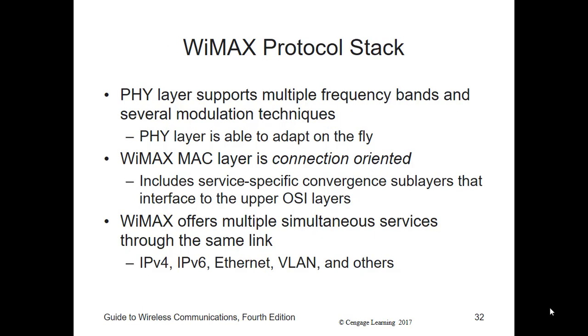As with many of the technologies that we've talked about, the PHY and MAC layers are the only ones that change between different networking standards. WiMAX is unique in that, in addition to the PHY layer supporting multiple frequency bands, its PHY layer is able to adapt on the fly. The modulation techniques and access mechanisms can change dynamically from the BS to the SSs, as well as to other BSs, depending on distance, the existence of any interference, or the requirements of the particular device itself. It has the ability to dynamically change.